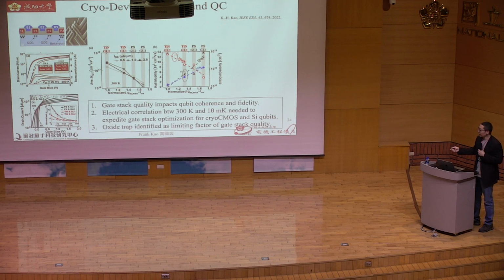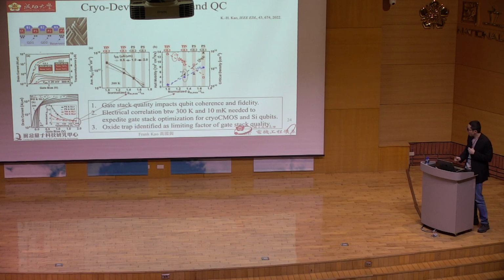Two types of gate stack, two different insulating silicon oxide layers, and two different gate electrodes, titanium nitride and polysilicon. We measure the IV curve at different temperatures from 300K down to 4K, and we extract their mobility at different temperatures. And we put the 300K mobility here.